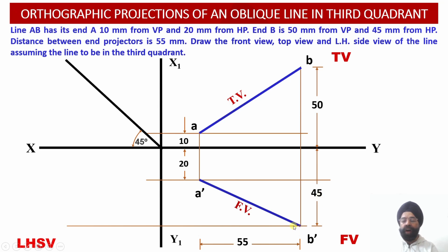So we have to draw a horizontal projection line in such a way that on this horizontal locus line corresponding to the point B dash, our point B double dash will also be lying on the same horizontal locus line. So the distances of the points A and B in the elevation decide the locus lines for the points A double dash and B double dash in the profile plane over here.